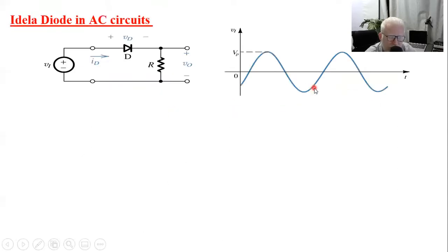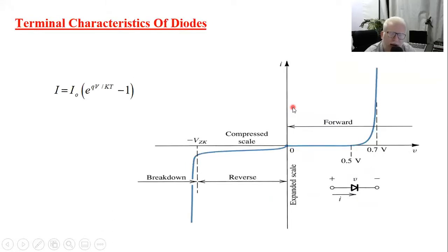Okay, this is the typical characteristic of an electrical diode. We have a very low voltage, nearly 0, whenever the voltage is smaller than V naught. Then the current starts to increase once we move larger than V naught, which is what we call the forward bias. While in the reverse bias, we have a very low current due to minority carriers, up to the breakdown voltage, then we have this breakdown. This is the exact characteristic.